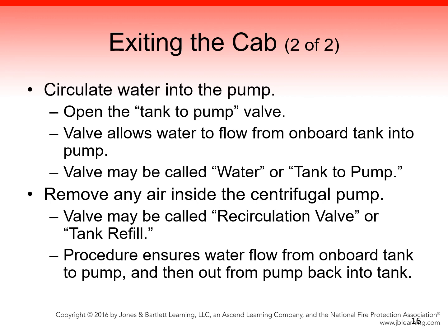At this point, water is flowing into the pump, but you need to remove any air inside the centrifugal pump for it to operate properly. This small positive displacement pump draws air and water from the top of the centrifugal pump. The centrifugal pump can pump only fluids, not air. Once the pump is primed, there is no air inside the pump.